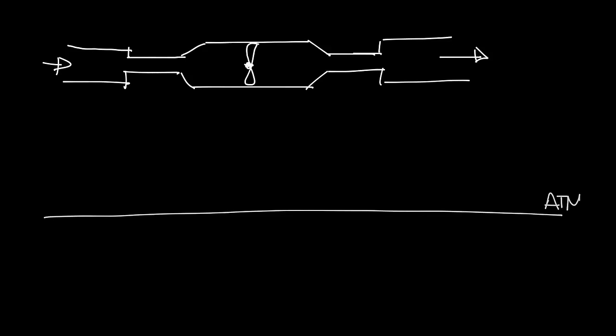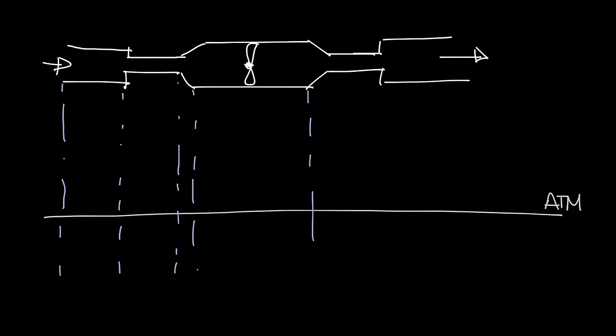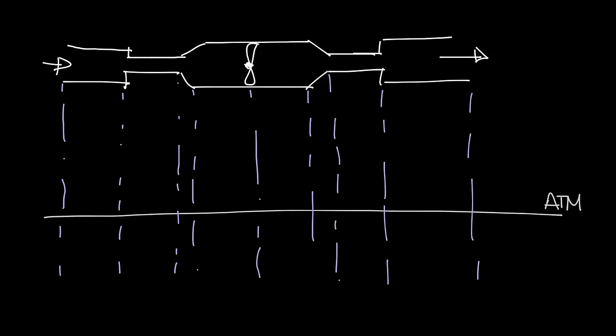Okay, so let's look at the pressure profile of this little piece of ductwork. I'll draw a line down here, and that's going to be atmosphere. So the air being pulled into the return, and the space that's being supplied, is just at atmospheric pressure. And now let's draw some lines down to show each of the transitions. So each place that something's going to happen with the pressure will have this little purple line.